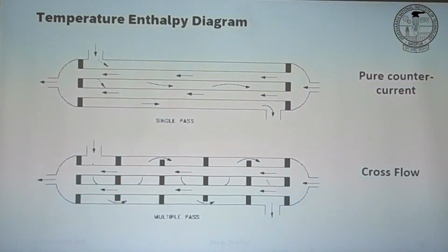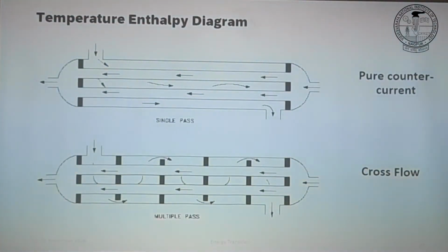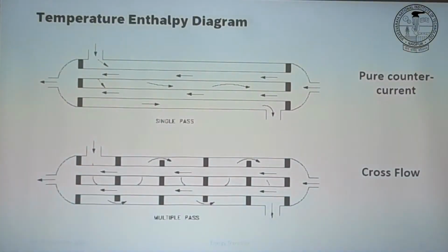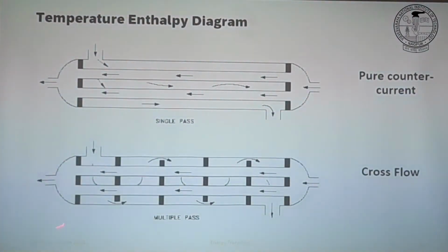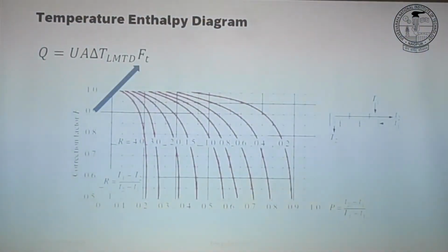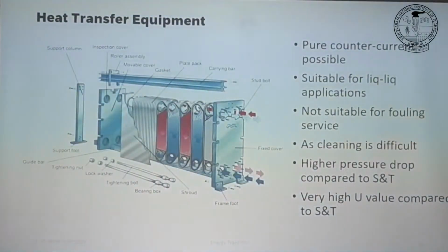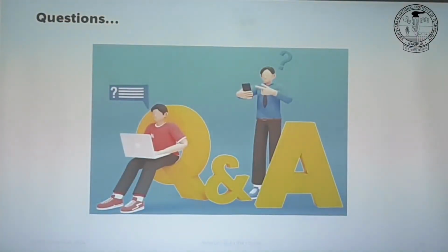We also use baffles to create turbulence within the shell. Yeah, because you are giving some more area in the shell, right? So that further turbulence is created. Yeah. So that is one way to understand it, if you agree. If you put it into the tube side, again they will have very little area to pass, and again turbulence and those kinds of problems will increase.